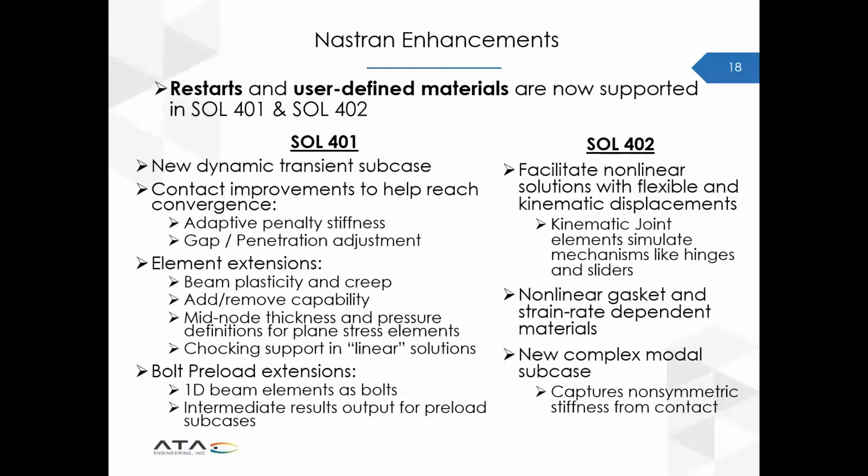And then finally for 401, we can now use 1D elements as bolts, and we can write out intermediate results for preload subcases. So this is some cool stuff that's going on. Moving over to 402, large displacement kinematic effects are supported better with kinematic joints.